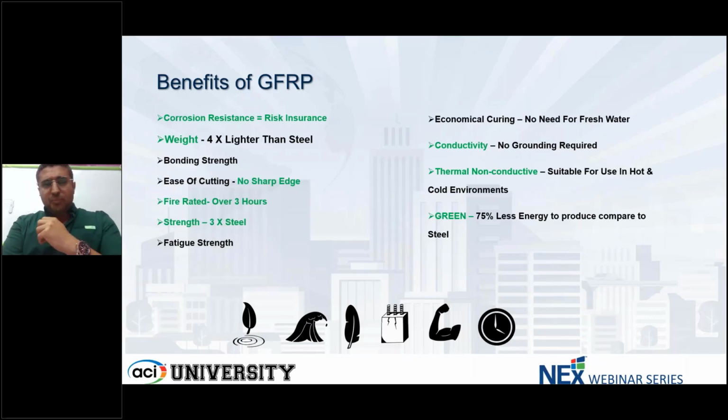On the other side, the material is beneficial because if you have a future opening, if you're designing temporary retaining walls, or if you're designing, for example, a tunnel application with TBM, tunnel boring machines, at the end of the diaphragm, when the tunnel boring machine is cutting through, fiberglass rebar composite materials are very easy to cut through, and that's because of non-isotropic material behavior. Fiber composite materials are orthotropic instead of being isotropic. That means they're much stronger in one direction and weaker in the other direction. So the material can cut through very easily.